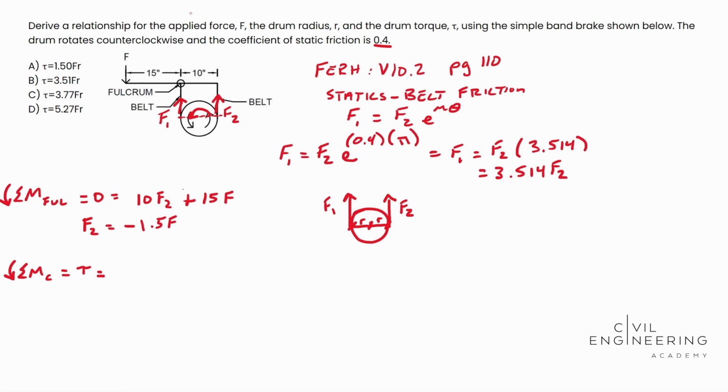So this guy, R is the perpendicular distance. The perpendicular force is F2. That's going to be a positive moment because it goes with our applied positive. And then we have that F1 actually acting against what we established to be positive. So that's a negative moment there. So we have minus R times F1. So there's that, and then the next step, well, looky here, we have something that we can use in our toolbox. We can use this formula right here and plug it in there.